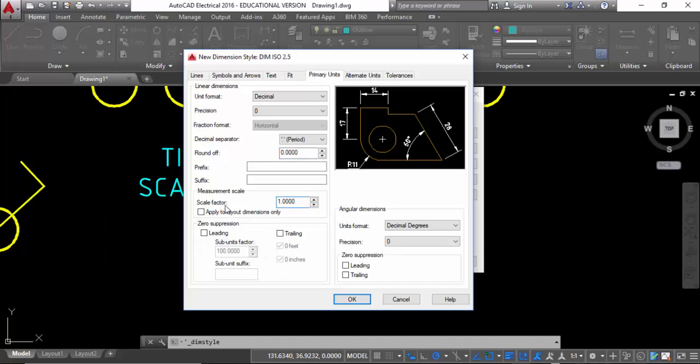The scale factor works very differently, so it works in this type of way. If you're working in your model space, which is this tab here, so we can see at the bottom left, model space, you use your scale factor. Now the scale factor here is going to determine what that object size is going to be. So you saw how we scaled down one of the drawings.